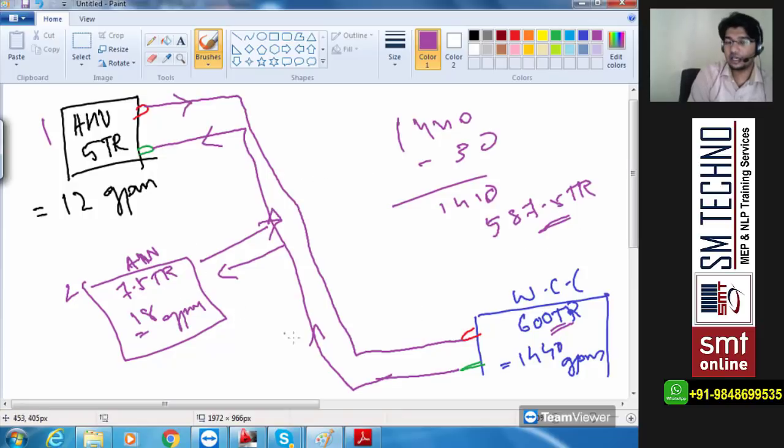All right. So why are we actually taking care of these calculations so deeply? Is because when your supply from the chiller is going to move, maybe your plan is going to have 10 AHUs at one instance. So now dependent upon the GPM level, okay, the GPM level is what you're going to decide the pipe size. Now we know that what is the main riser of a chiller? Which pipe is called the main riser? From where the water is actually supplying, the main opening of the supply connection. So I can call that this is a riser, right? This is the main connection here, the pipe where the water is moving inside.